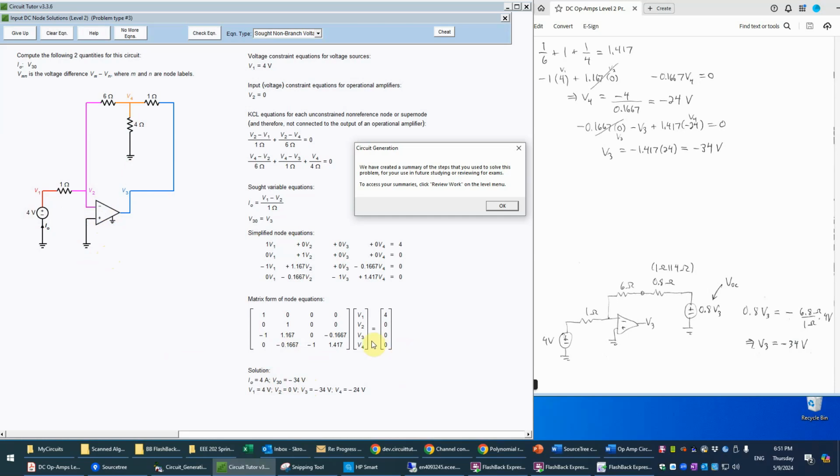Okay, now the other thing is, how could we understand this circuit more simply? I think that's really worthwhile doing. If you think about it, it's a lot like an inverting amplifier, except for this extra resistor here, which confuses matters. So how could we account for that? We could use one of the basic ideas that we've learned in circuit analysis. Namely, we've got some sort of source supplying the voltage V3, and then what happens to that? Well, it's being fed back here, and you'd say, how could we represent all of this in a way that would make it easier to understand what's going on? And the answer is we could use a Thevenin equivalent circuit, which is a very useful thing in all types of circuit analysis.